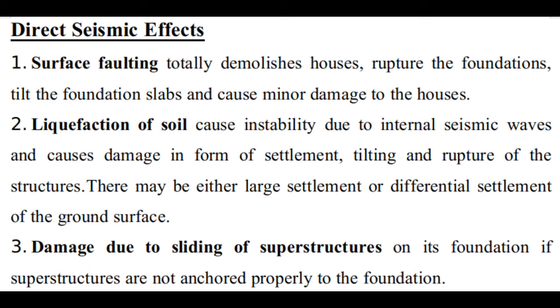Second one is the liquefaction of soil. As I have just explained a few minutes before, the liquefaction of the soil causes instability due to internal seismic waves, and also causes damage in the form of settlement, tilting and rupture of the structure. There may be either large settlement or differential settlement of the ground surface. Third effect, damage due to sliding of superstructure on its foundation if superstructures are not anchored properly to the foundation.